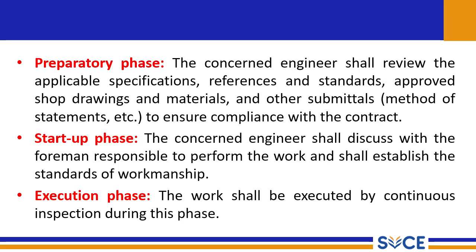So, preparatory phase: the concerned engineer shall review the applicable specifications, references and standards, approved shop drawings and materials, and other submittals to ensure compliance with the contract. Startup phase: the concerned engineer shall discuss with the foreman responsible for performing the work and shall establish the standards of workmanship. The execution phase: the work shall be executed by continuous inspection during the phase. These are three important phases here: preparatory, startup, and execution phase.